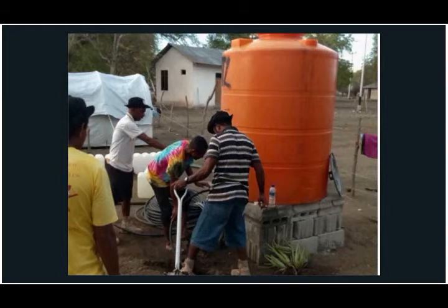To go beyond that, when you're doing groundwater, you would have to do groundwater pumping tests, which measure the drawdown of a groundwater level. However, what you then need to think about is what the other impacts are, so what are the other boreholes within your vicinity that are also extracting water from the aquifer. And there's an impact with regards to rainwater and how much the aquifer is being recharged.